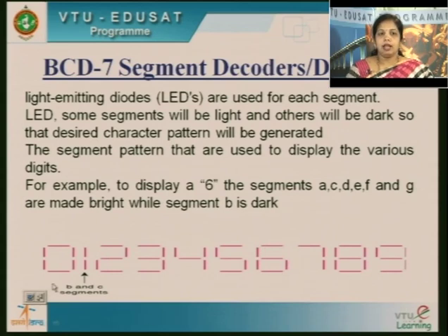Similarly, I can display from 0 to 9. Based on what pattern you want to display, that particular segment will be made high or turned on. You can see here, for 1, B and C segments are used. Like this, we can generate a pattern using this 7 segment.